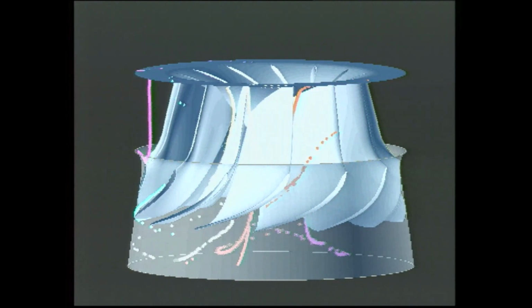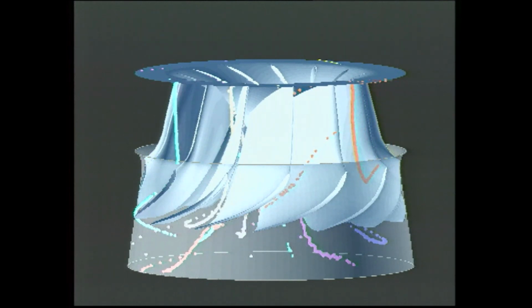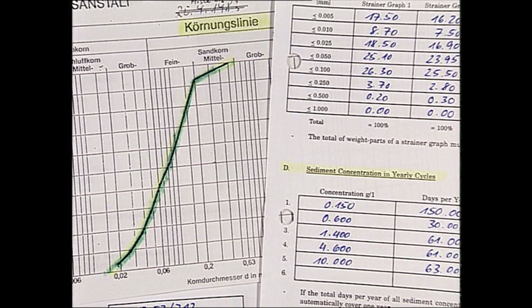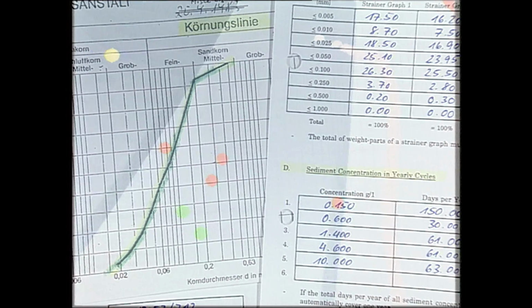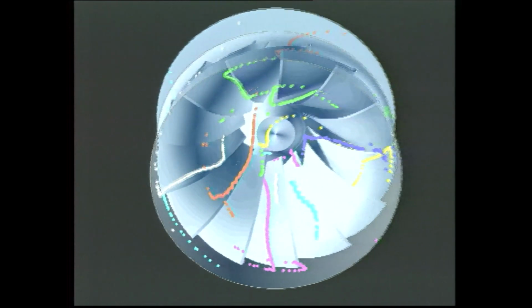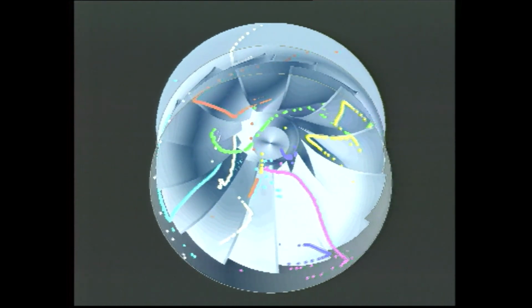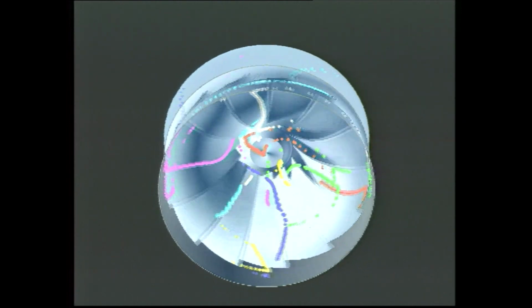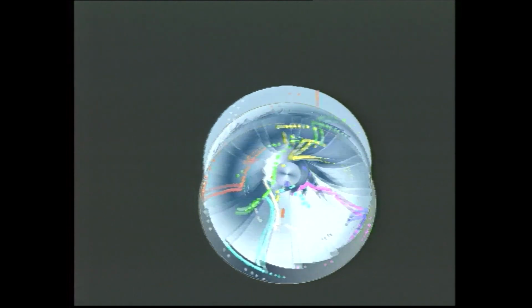To simulate the conditions of a particular project, Voith Siemens hydropower generation requests comprehensive information on sand characteristics, particle gradation, and so on. Inserting such a customized collective of sand particles into the numerical flow field yields reliable statistical information on the frequency and the location of particle impingement.